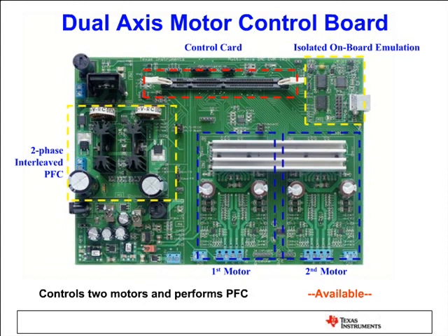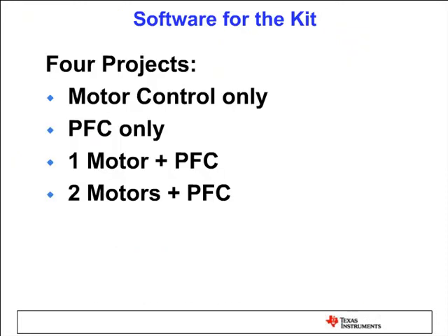So far I used the 2808 Piccolo A and Piccolo B with this card, so the customer can evaluate any controller he wants to use. And the yellow part is the PFC stage. Using this board, the customer can experiment with single motor control, PFC only, 1 motor plus PFC, 2 motors plus PFC. So right now we have all these combinations.